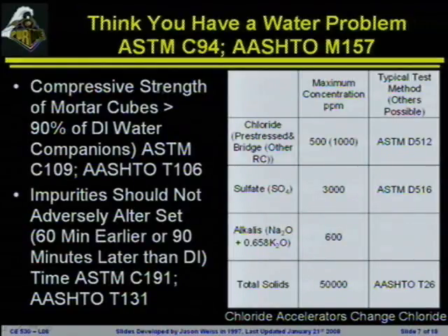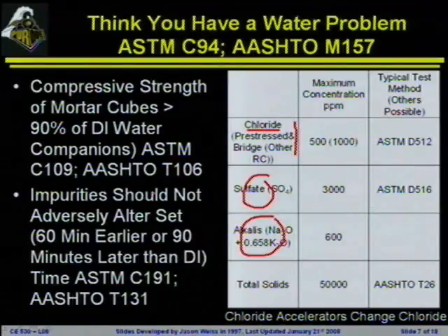As I mentioned, the main things that you're going to want to look out for are any alkalis that may be in the water, any sulfates, and specifically when you deal with places near the coast, any chlorides that might be in the water. Chlorides have a little bit of a nebulous history in concrete. For many years, chlorides were actually put in to accelerate the strength development in the concrete, but this is a big no-no because it's also going to accelerate the corrosion. There are several buildings that are undergoing corrosion problems because someone put it in as an accelerator.